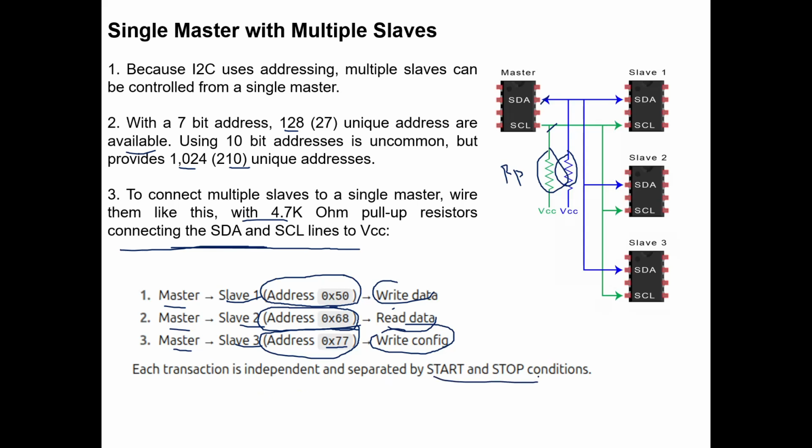While doing a write operation, it will do the start and stop condition, and during that only it is sending the write operation. And then if you want to do the read operation, then again, after it is stopped, it is communicating again, sending some address and then the read or write operation, and the data frame it is receiving. So reading operation is doing that. And similarly, write configuration: after stopping the read operation, it will do that write configuration. Clear?